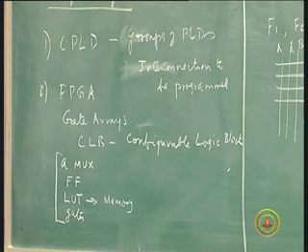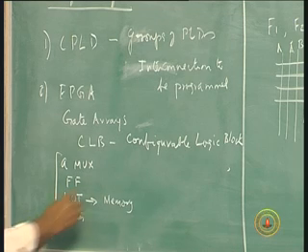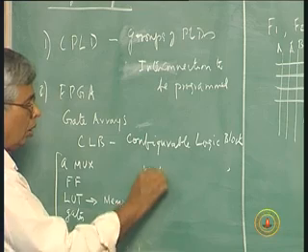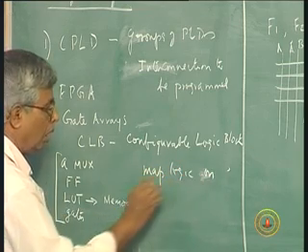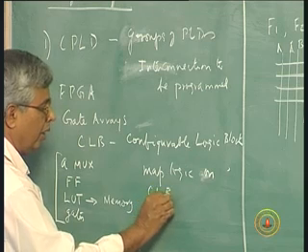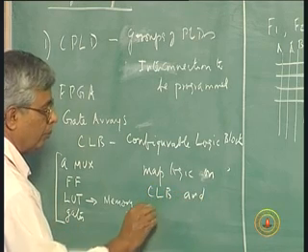Your job is to break your design into these smaller groups and then interconnect them efficiently. So, you have to map logic onto CLBs and also interconnect them.